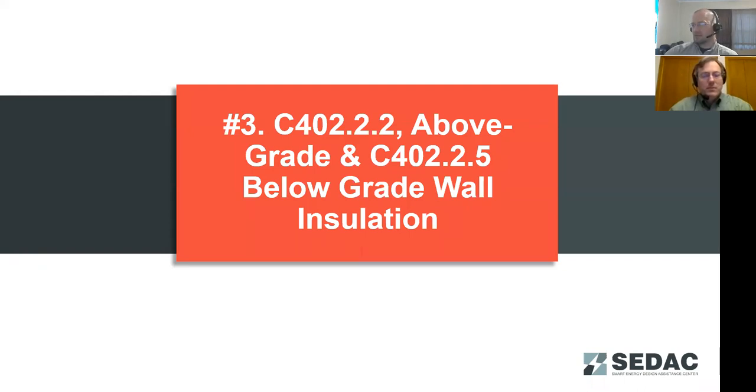But I would think as long as you've got 2 layers of offset joints for that roof and you're meeting your R value requirements, that would count for that offset. But most roofing, in order to meet their R value requirements, are going to have more than just 2 layers of insulation in most instances, in which case each layer is going to be staggered. So you're going to have multiple layers, and each layer is going to have the joints offset.